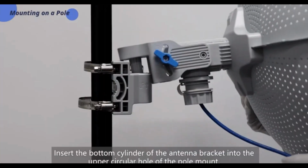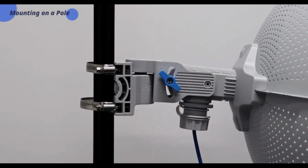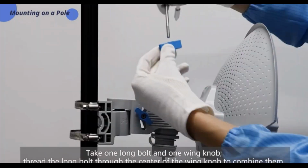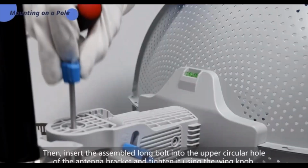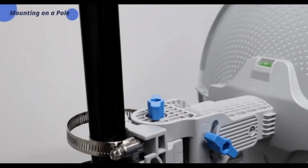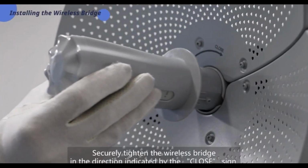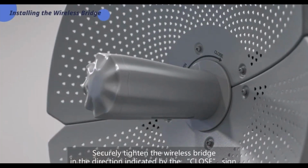Insert the bottom cylinder of the antenna bracket into the upper circular hole of the pole mount. Take 1 long bolt and 1 wing knob, thread the long bolt through the center of the wing knob to combine them. Then, insert the assembled long bolt into the upper circular hole of the antenna bracket and tighten it using the wing knob. Align the peg on the wireless bridge with the slot on the assembled reflectors. Securely tighten the wireless bridge in the direction indicated by the closed sign.